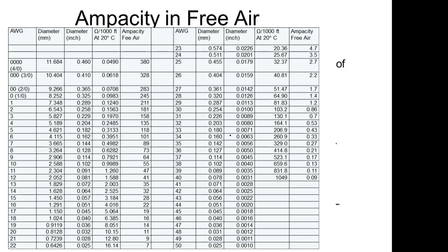What other things would have an effect? So what's the term ampacity mean? What do you think that means? It's a combination of two words. Yeah, it's amp capacity. So it's the amperage that a conductor can handle. A conductor doesn't deal with volts. A conductor deals with amps, right? That's what it's trying to get from the power source to your house.